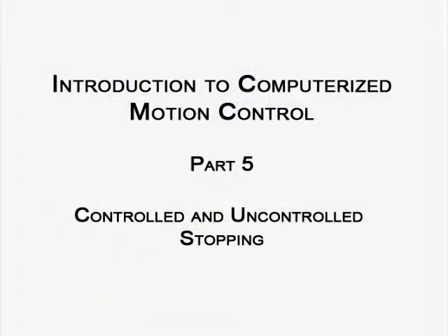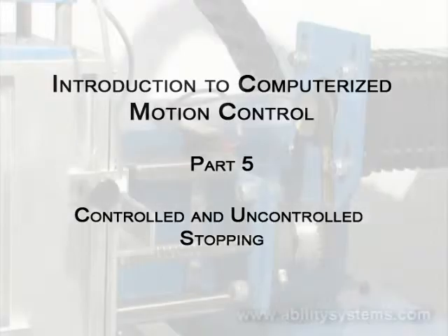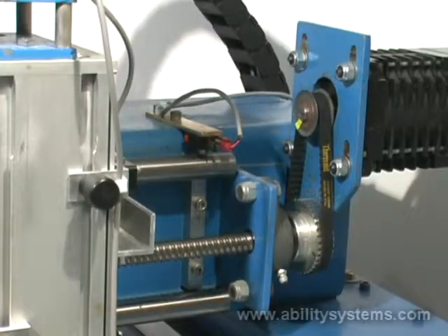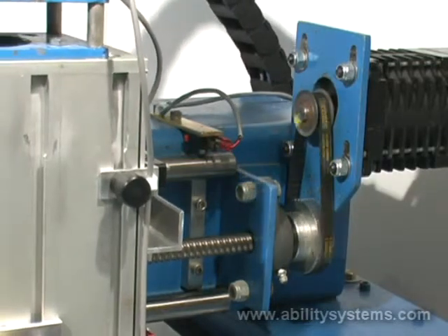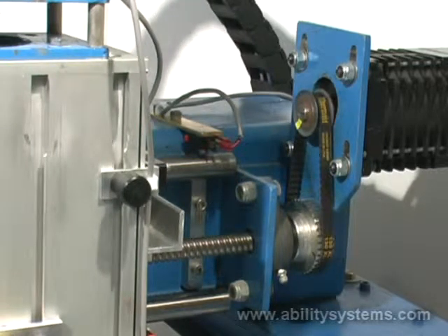In the previous session, two methods of stepper motor motion were explained. The first method, which we called instantaneous, applied a fixed frequency pulse rate to the translator, which moved the motor shaft at a constant speed. The ability of the motor to accelerate to speed within the boundary of the first and second step position limited the instantaneous speed that the motor could attain using this method.